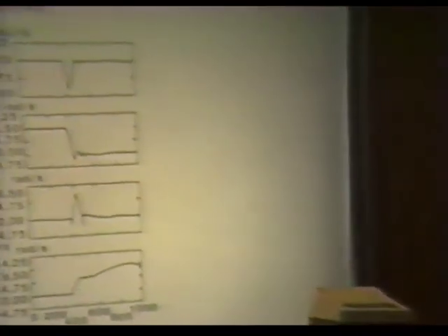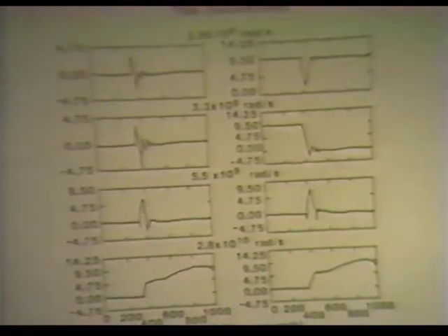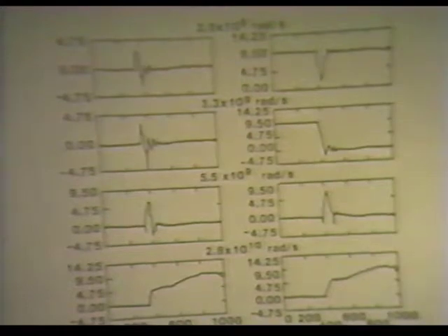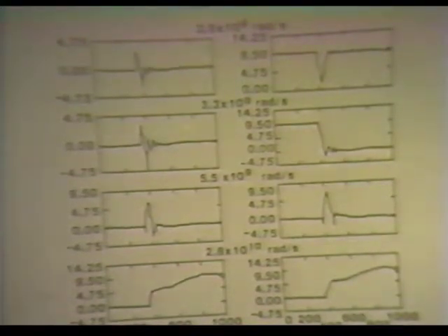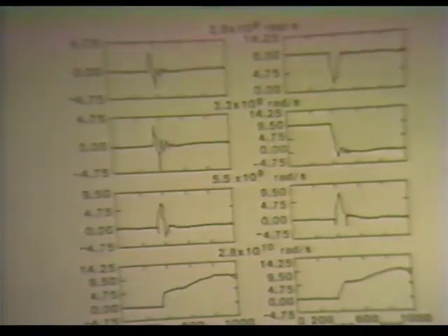Is it typical to find something that will upset at a lower dose rate, not upset at one a little higher, and then not upset at the next one? Generally, you don't see that. Usually when they hit upset, they will upset at every dose rate above that too. Now they may not always come back to the same state after you upset, but they usually will upset, yes. You really mentioned total dose, but it's really dose rate. Yeah, this is dose rate that we're looking at, rads per second and not rads.